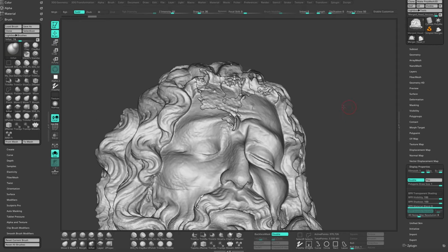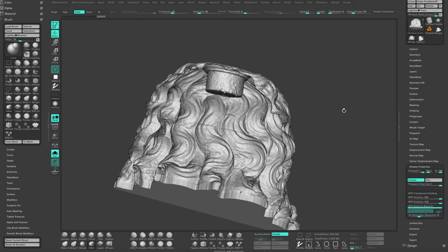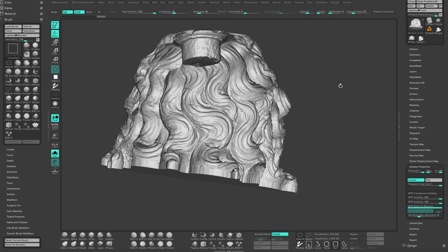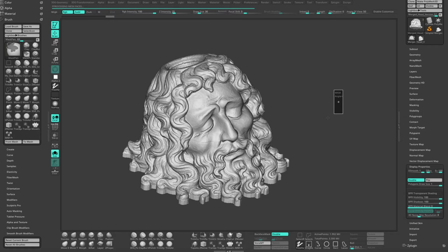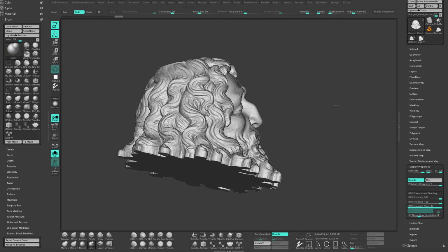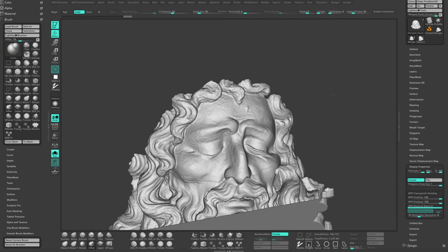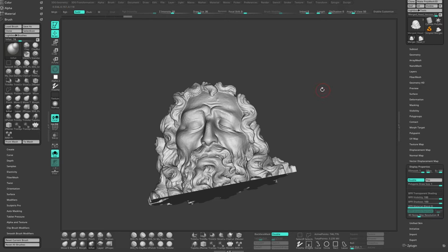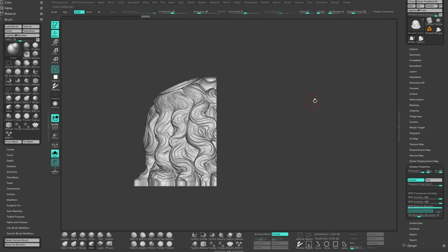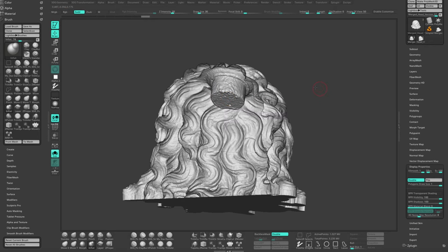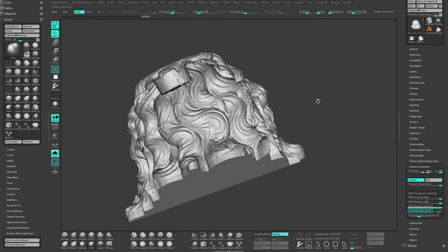This allows you to locate the holes on the outside and close them, and then we should be good to go to run dynamesh one more time. So I give ZBrush a second or two to make its calculations, and then I again isolate parts of the mesh, and as you can see now, the chunks of geometry we previously had on the inside are now gone, and the model looks pretty perfect. This part, of course, comes from the opening or the indent at the top, and this is perfectly fine too.